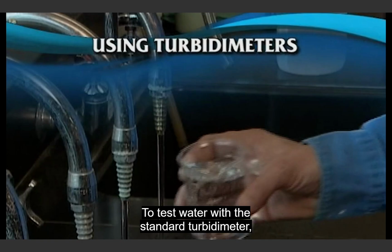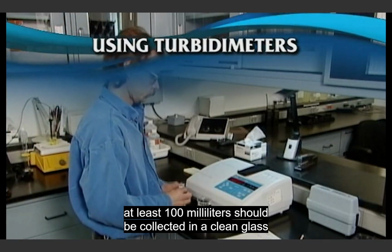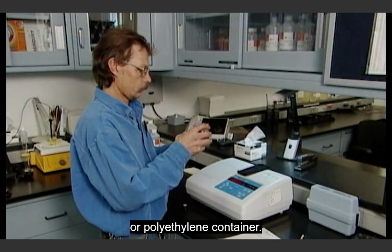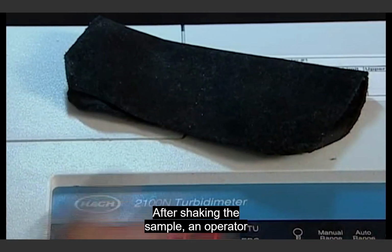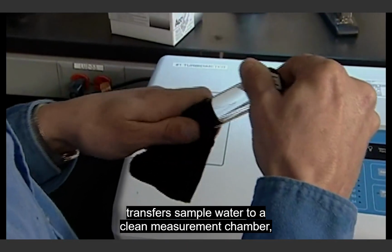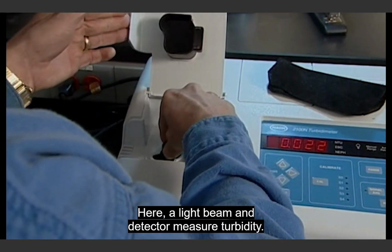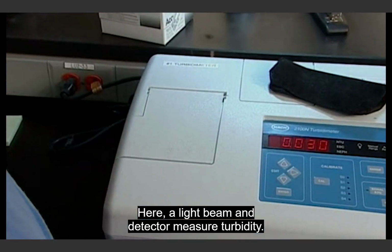To test water with the standard turbidimeter, at least 100 milliliters should be collected in a clean glass or polyethylene container. After shaking the sample, an operator transfers sample water to a clean measurement chamber, which is placed into the turbidimeter.